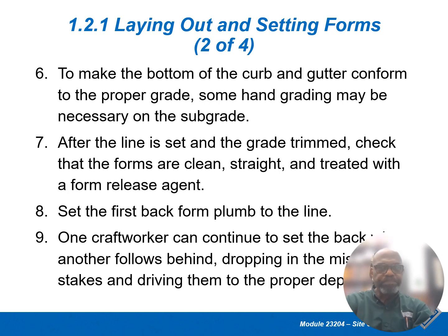Number 6, to make the bottom of the curb and gutter conform to the proper grade, some hand grading may be necessary on the subgrade. And the subgrade is the base. It's what you're putting down, what's been compacted. It could be sand with aggregate on top of that.